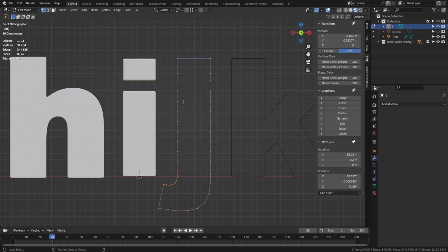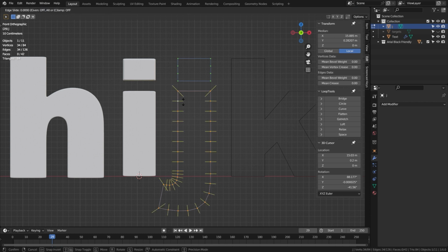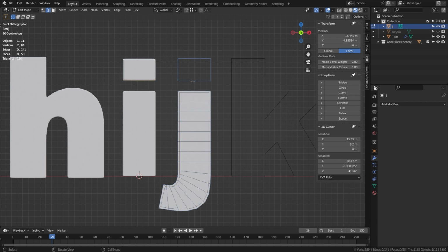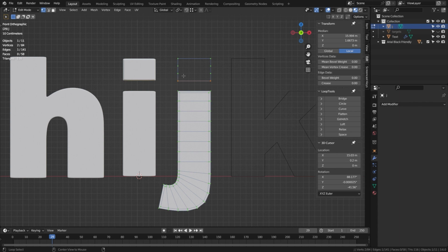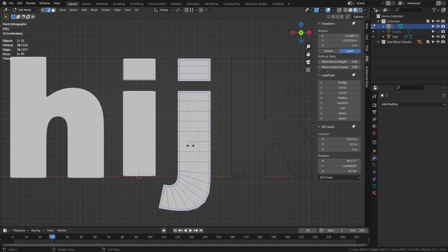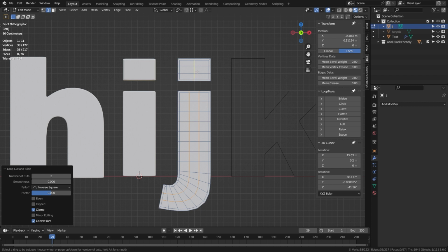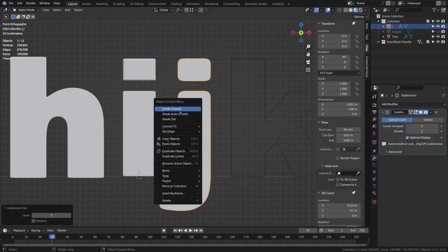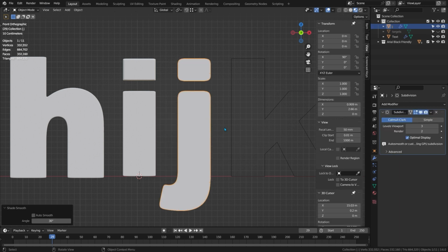Alt and click on an edge inside. GG, Alt, -30, enter and let go of Alt. Switch to edge mode with 2 and fill in the faces from top to bottom and again on the dot at the top. Now the internal geometry, just Ctrl and R, roll the mouse for 2 loops and again at the top. Press A and Shift and N for the normals. Tab, Ctrl and 3, right click and shade smooth. And then tab back to edit mode.